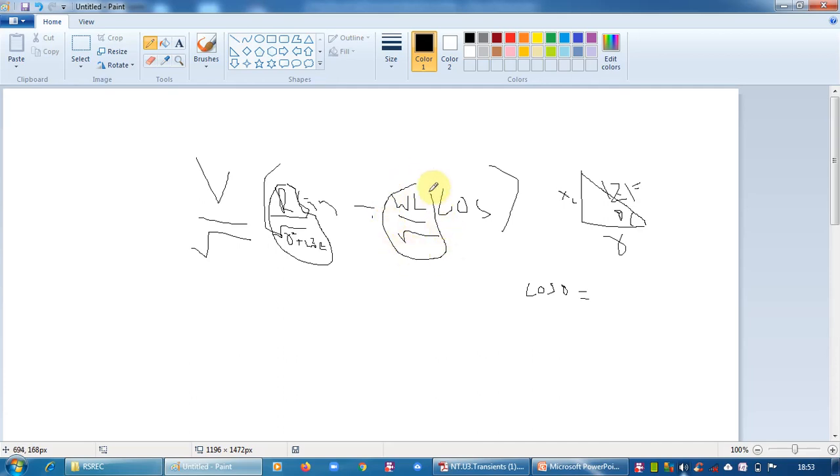Similarly for this, XL equals omega L, what can we replace? Sin theta. Sin theta equals XL by Z, opposite side by hypotenuse. So this is equal to sin theta, and this is equal to cos theta from the impedance triangle, where theta is the impedance angle, R is the resistance, the real part, and XL is the reactance. For an RC circuit, in place of XL we will get XC, that you have to remember. XC means 1 by omega C. There also the same thing; the difference is only that.